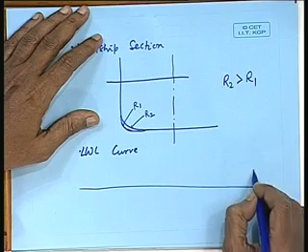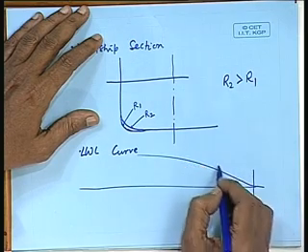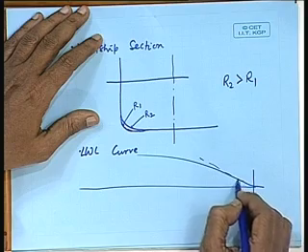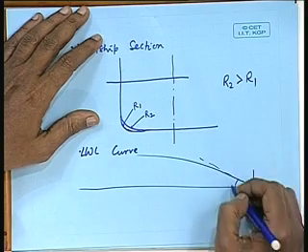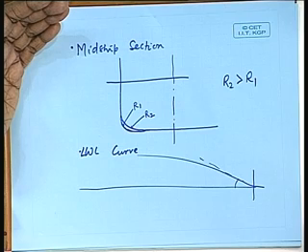Half angle of entrance we talked about, that determines how smoothly the hull is going into water and what will be the wave crest. So, LWL, if it is smooth at FP, if this angle is small, half angle of entrance is small, then it is always advantageous.